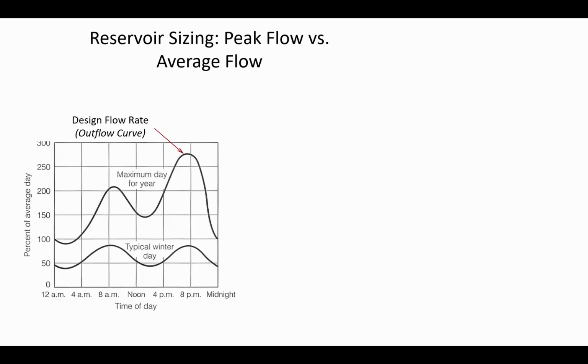If we wanted to know the flow into the reservoir, in a 24-hour period, let's assume that the flow in equals the flow out of the reservoir. Now this is a really important idea. This is an application of the continuity principle, and what we're saying is that during a 24-hour cycle, the flow into the tank and the flow out of the tank is the same.